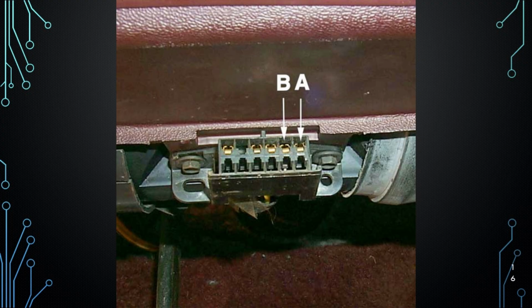That connector is a GM OBD1 ALDL, assembly line diagnostic link connector. It was used for pulling codes. A and B were terminals you could jumper to make the check engine light flash out stored codes. It allowed basic diagnostics, no live data, but you count flashes to read trouble codes directly from the dash light. Okay, very good. Actually, you hit that one right on the head.